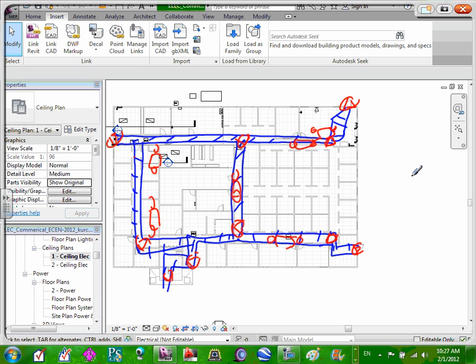Do you commonly use battery backup or generator backup? Like if you have a generator within 10 seconds. If it's a brand new building, we usually use generators. And then you use just one fixture for emergency and normal? Yes, and then we put in a switching relay. So you walk into a classroom and you can switch the lights on and off, and you don't even know which fixture is emergency.